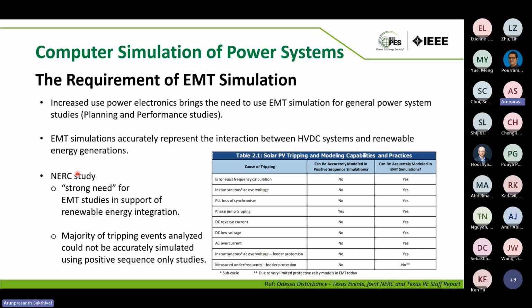And also from the study, they found out that the majority of the tripping events when using solar PV inverters could not be accurately simulated using phasor-based simulation tools. So we can take a look at the reference here to find more details. So basically, an EMT simulation tool is recommended for studying the practical power system that we have now.